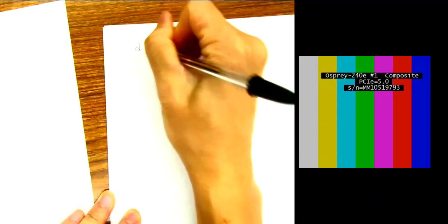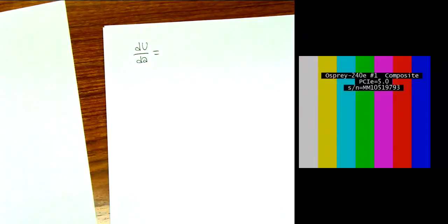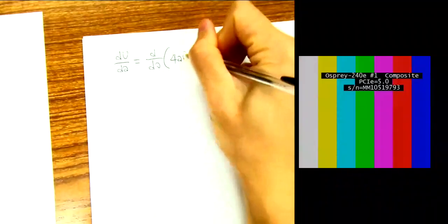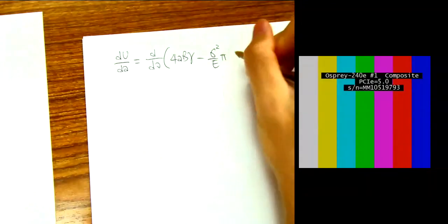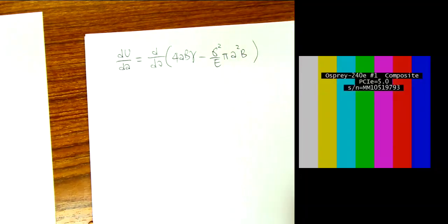What we want to calculate is dU/dA. We want to differentiate that expression with respect to the crack size. Now in this process, our stress is constant. Just keep that in mind. We are not changing stress. We go to the stress and then we stop there.